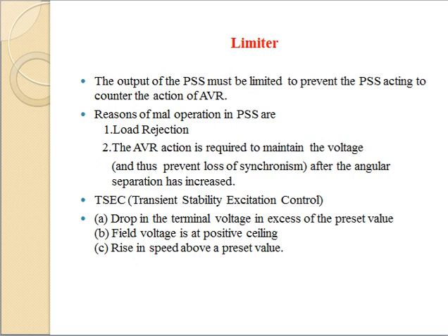But at the outset, the PSS may see it as a requirement for action, and it will take action. So there will be counter actions from the PSS and AVR, and then mal-operation will occur. Another thing is that AVR action is required to maintain the voltage and thus prevent the loss of synchronism after the angular separation has increased. In this case also, if the PSS tries to take some action, mal-operation will occur.